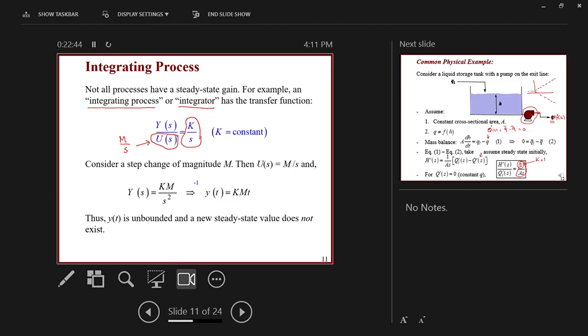If we take the inverse Laplace of that, we get the final time domain form of the dynamics of y with respect to t. Now km here is not the steady state value as in the first order process. It actually represents the slope of change. This kind of process will behave this way if we have an input. Let's draw the process.